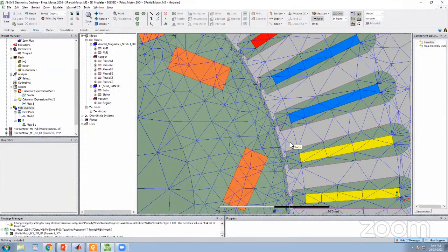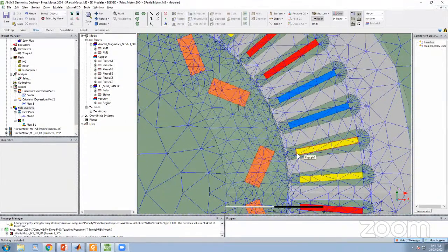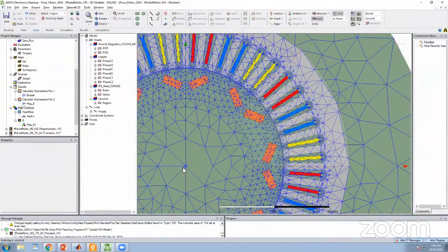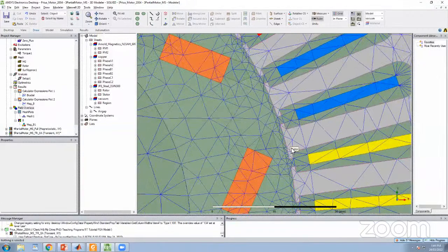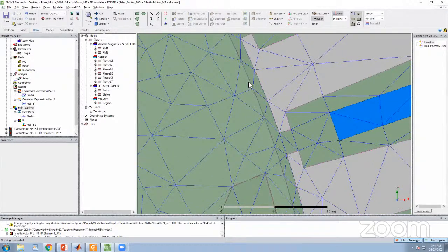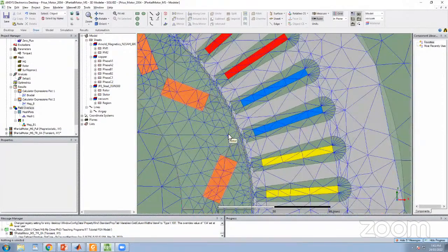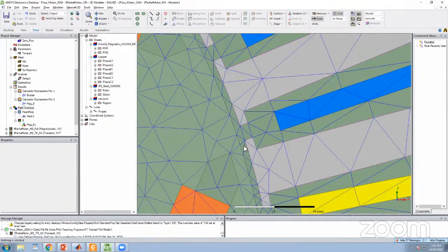When you do enough FE simulation and you look at the model, you will know whether this is okay or not. Actually, if you ask me, my personal opinion, if I use my standard to examine this, I would prefer to make the air gap mesh finer, meaning we need to have smaller triangles in the air gap. But because many of you are using the student version of ANSYS, I guess this is the best setting you can use, and we can still get a fairly accurate result. So it is okay.